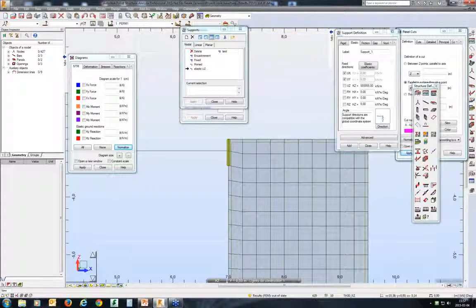On the other hand, if it is a wall intended to transfer or withstand horizontal forces, defining that as a column in a single node, having a single node connection to the slab, may also not be the best solution, because actually you need this width to transfer horizontal forces correctly.